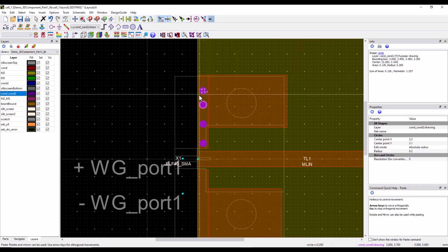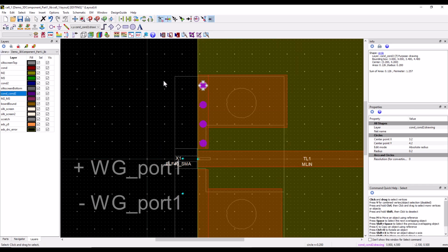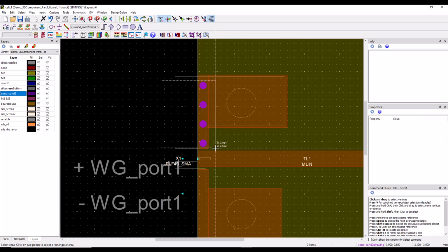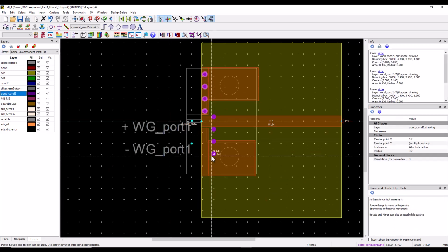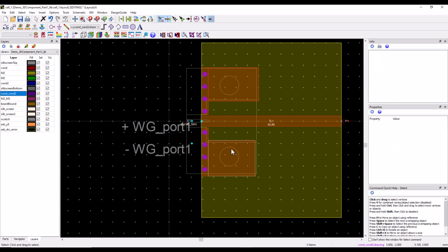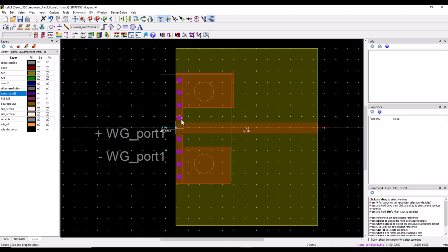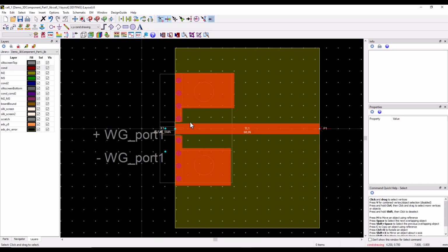Now when you're trying to design an optimal transition, of course you will do the proper placement of the vias, but here I'm just showing you the basic concept of using a 3D component in ADS. So I haven't put enough attention on the separation, the via to via separation, and so on. Okay, so now everything is set. Now we can launch RF Pro and see this geometry in 3D, because we already have the connector, the transmission line, and the ground connection.